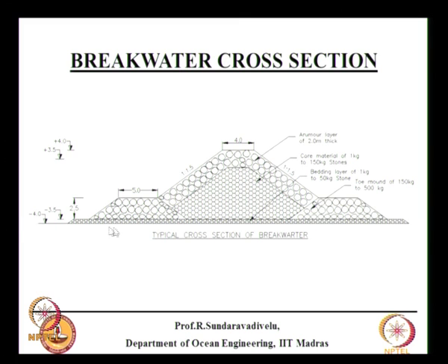Once you put a geotextile filter, the whole unit acts as a single piece, otherwise the foundation is discontinuous. The geotextile filter is a continuous thing. It is available in 3 meter width, and about 200 meters may be available in a roll. When you are laying it, you overlap and stitch it and lay it, that means you have a continuous layer here, whereas the foundation is discontinuous.